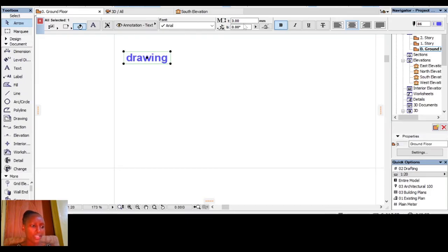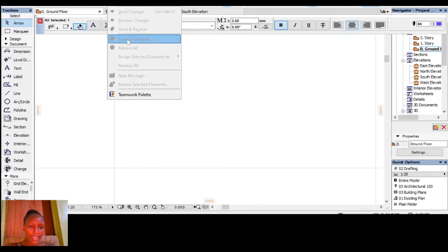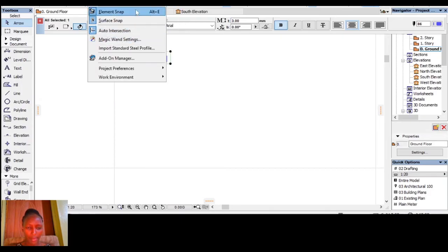There are also line types. You can set this characteristic for each line type or fill pattern in the line types and fill types dialog boxes. Also, the line types and the fill types will not change in size, but we are told that we can change these characteristics by going to Options, then you go to Element Attributes.